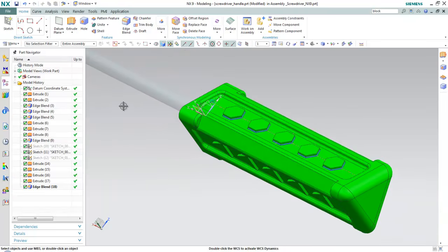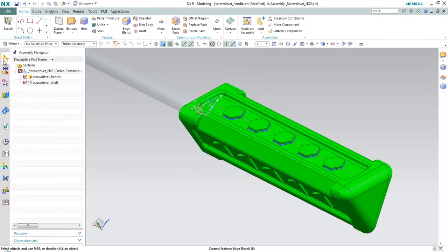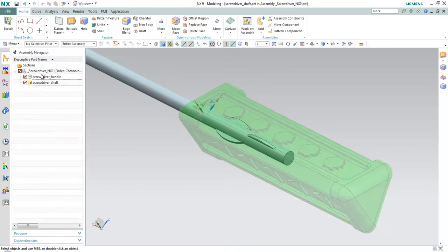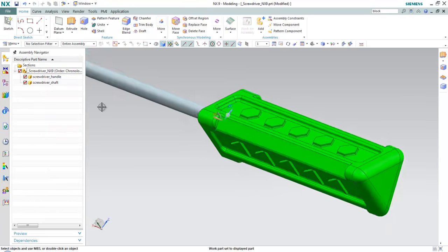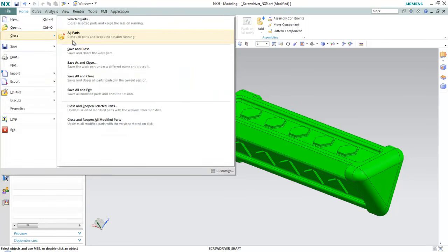So keep in mind that filter. It's a nice way of grabbing multiple edges, but it's also a nice way if something changes and it'll update, because it's not looking for a specific edge, it's looking where that feature meets the adjacent face.